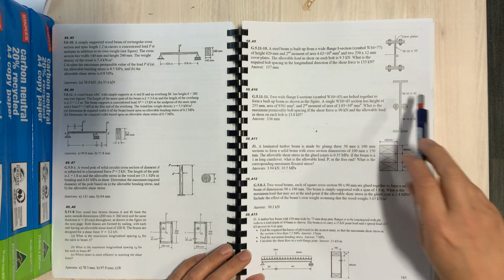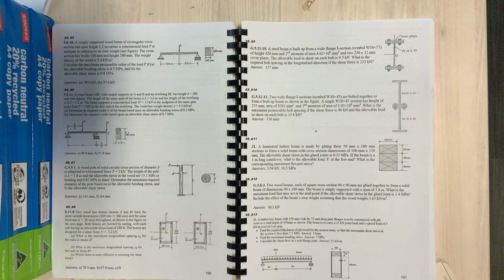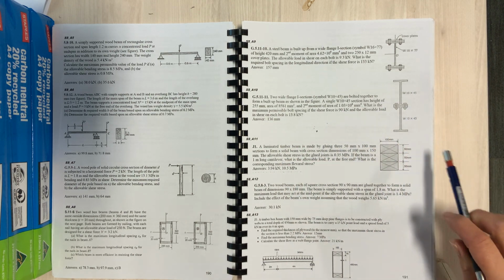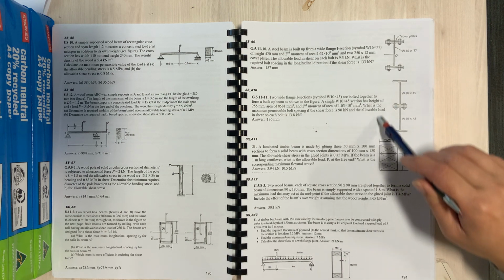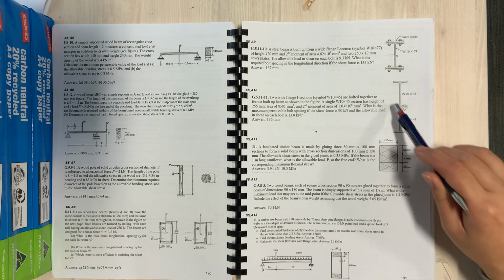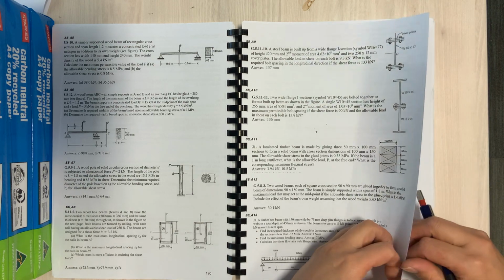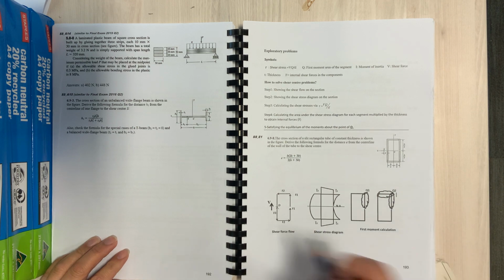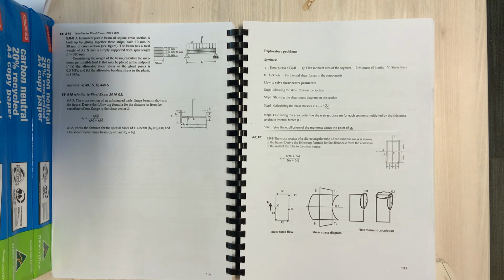So we've got an example here. This one here, I do remember there was some questions on that one before. It's given the second moment of area of the single section, and then you've got to use the parallel axis theorem at some stage to get the second moment of area of the new section. So it's things like that which can be of concern. And then there's that one there for a wide flange beam.